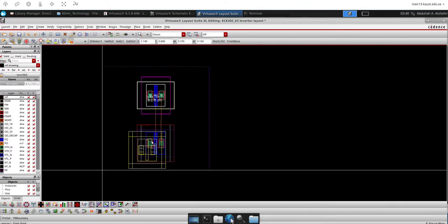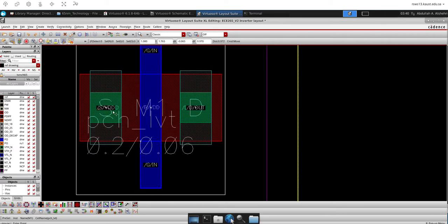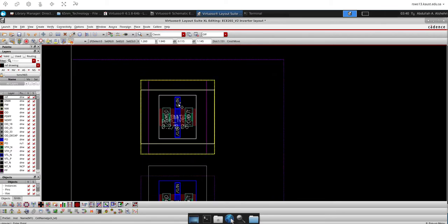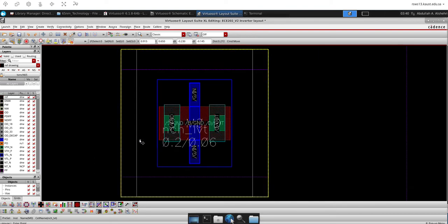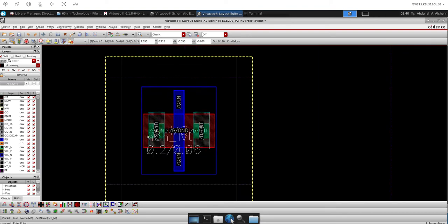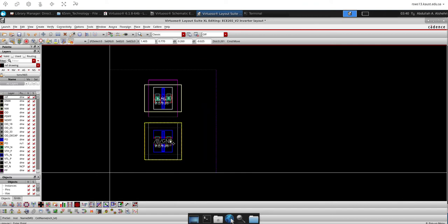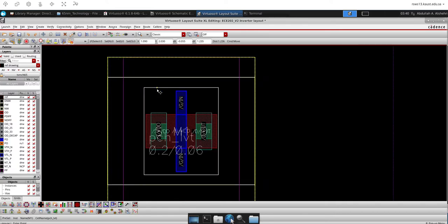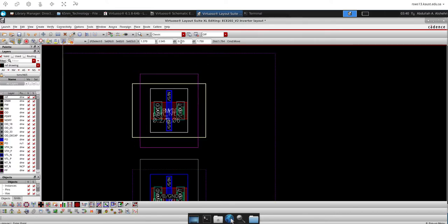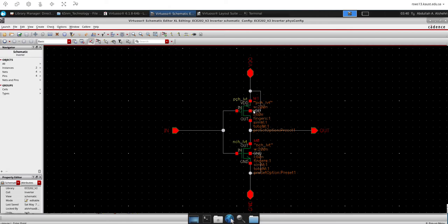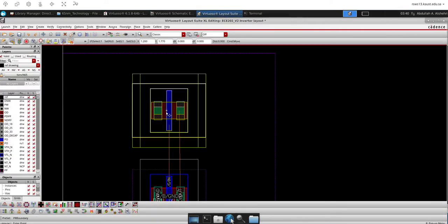M, take this one, make it aligned properly with the two transistors. So now this is source, this is drain. You can sweep it from the properties. It is the same drain, so we need to connect the drain together, and S to the ground and the other S to up, and we need to have a body. So this body is connected to the source, and this body is connected to the source, but here we don't have a body, so we can press on it, Q,